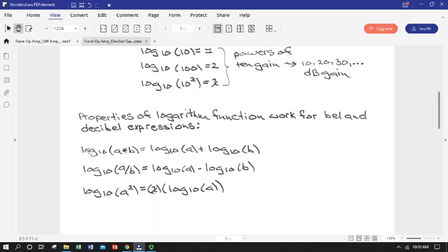So that's really handy if you're trying to solve for, say, the decibel equivalent gain of a cascaded amplifier. If you remember, if we take the output of one bipolar junction transistor amplifier and we apply it to the base of another, we're going to end up with a cascaded amplifier configuration, and so the gains will multiply. So we'll have beta of amplifier 1 times beta of amplifier 2. Well, if we wanted to get the equivalent decibel gain of that, if it was a BJT, we'd have beta 1 for A and beta 2 for B, and we would take the log of that.